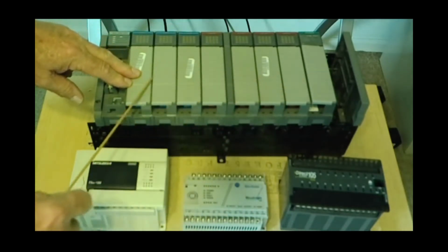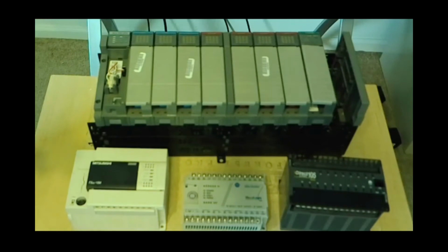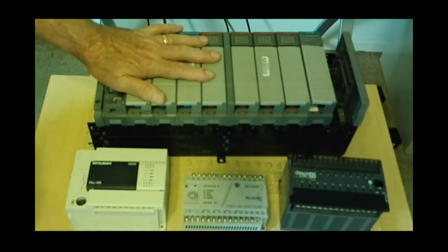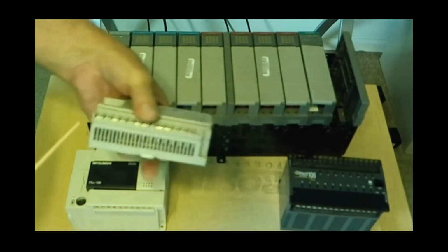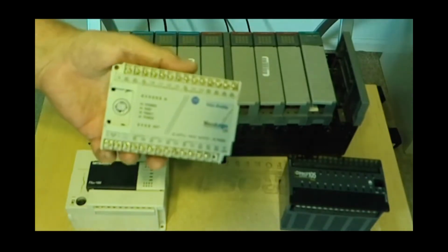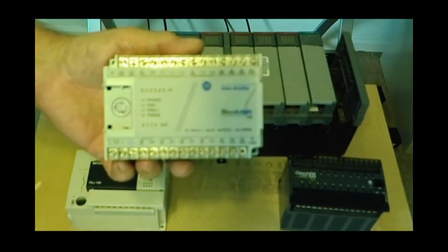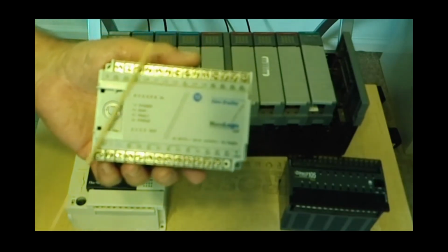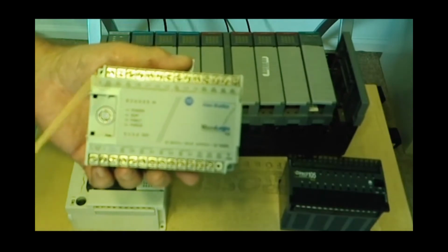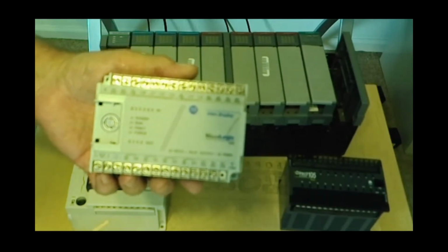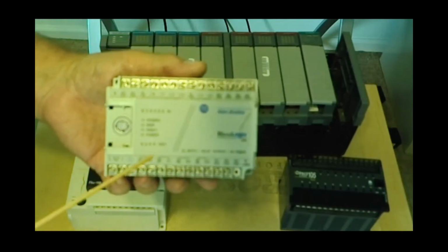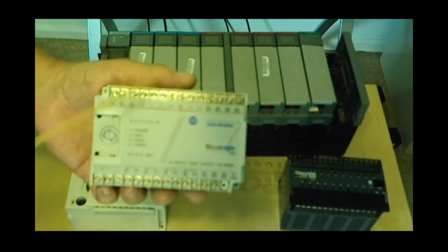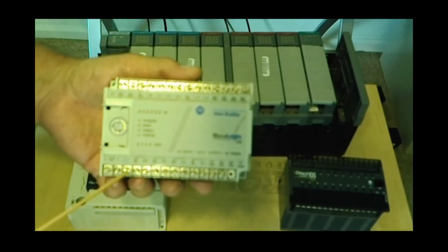So right here, rack systems are pretty common in industry and probably the most complex and most common you're going to see. Now, these little things right here in the middle called bricks do the same thing that the rack processor is going to do, except they cannot be expanded. If something breaks or goes bad on this, you take the whole thing off, throw it away, and put in a new one. But these are limited. You have all these different terminals. A lot of these are not used because it's just a standard box for these guys.